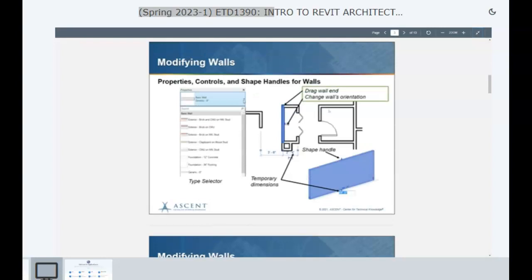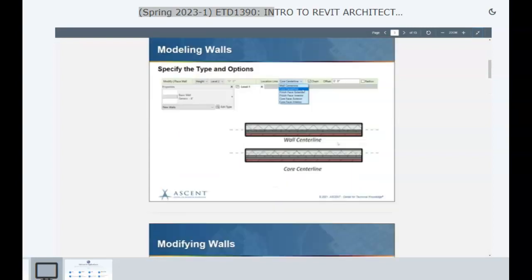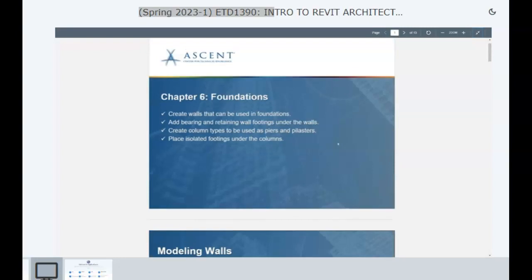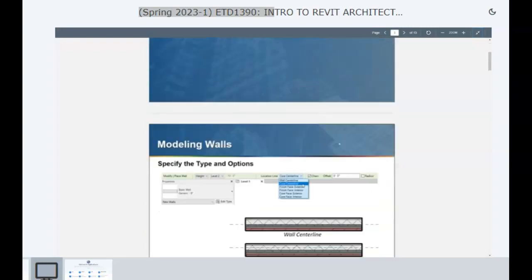When you first make the floor plan, the first thing you do is to draw on level 1 and create the floor plan. And then you start punching into the ground. You draw over your existing plan, and add in a foundation wall to create the bottom. So the floor plan, basic floor plan, is the generator of the other things.